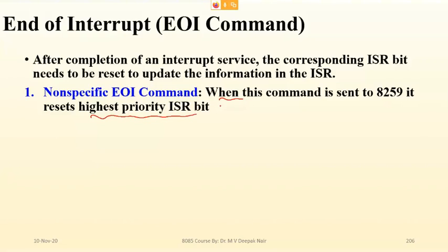That means whichever line is the highest priority interrupt being served at that time will be reset by using the non-specific EOI command.